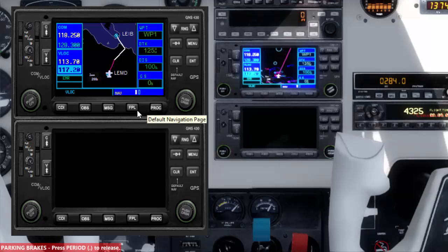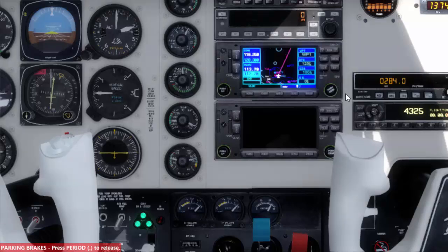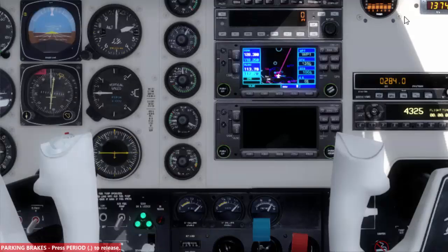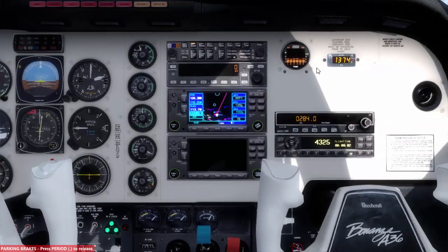Okay, and I want you to remember, please, the thing of altitude and elevation, because that is very important. You need to calibrate your altimeter. Okay, if not, it won't work, and you can get that information through the ATIS.